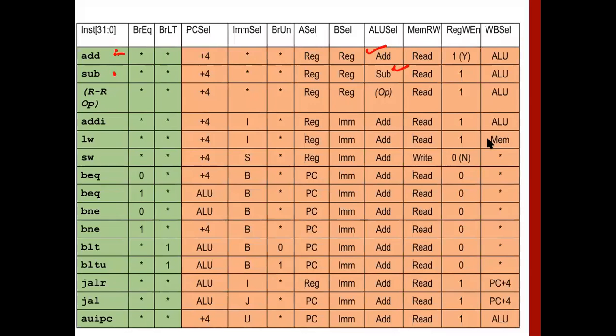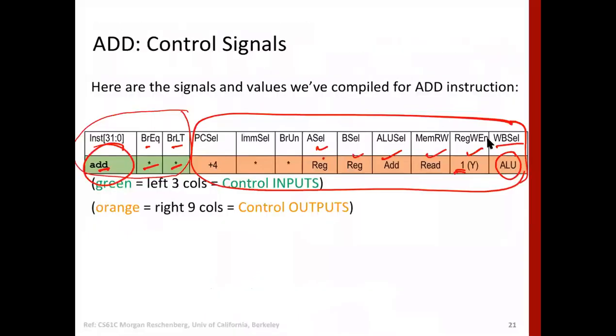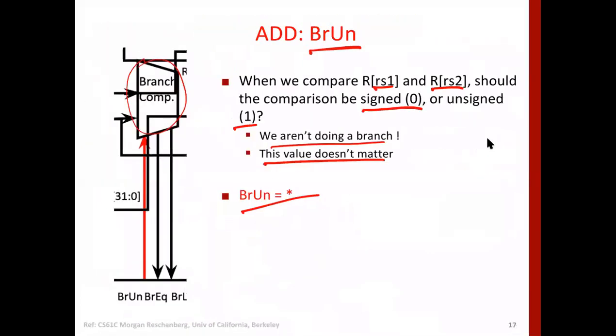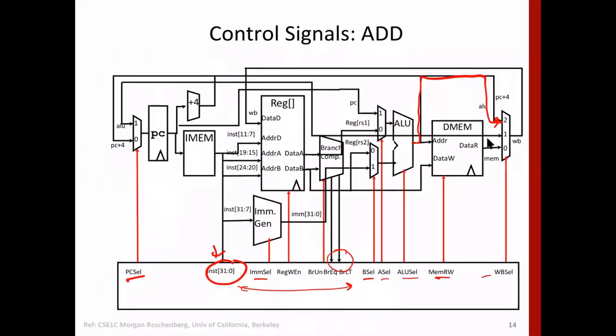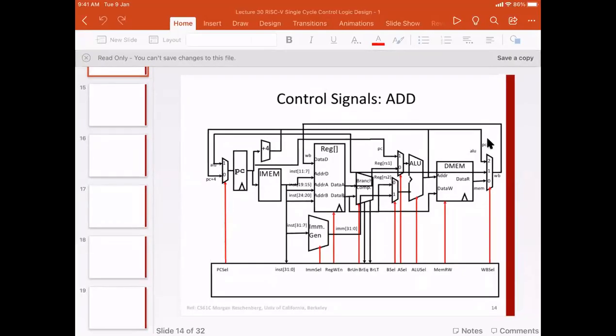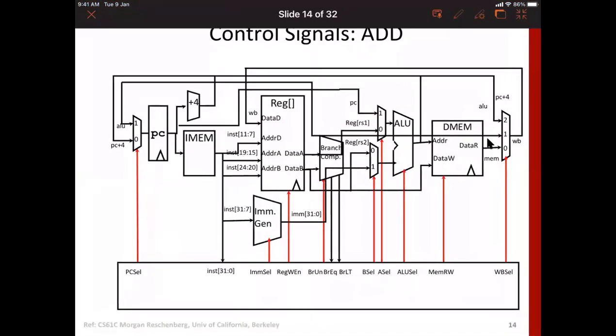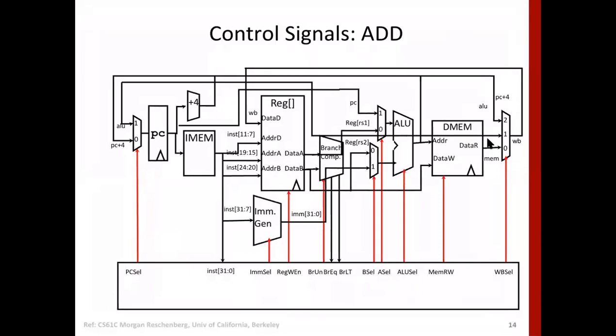In case of a branch instruction, if branching is not taking place, then we'll have to increment PC, right? But how will we do that? Because we are connecting that line, which is the output, directly to the multiplexer, and we are selecting the bottom one of the multiplexer. Shall we go to the previous diagram? Okay, let's go here. What we have shown here is for the add instruction, not for branch.